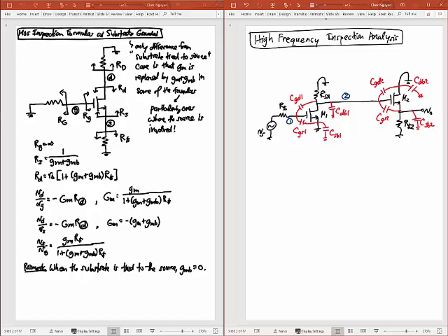And so I want to do this using the Miller transform. So I'm going to take any capacitor that is in a feedback position and turn it into Miller capacitors, because I don't want to memorize that driving point resistance for CGD, which is going to be the same equation as for C mu for a bipolar transistor. Okay, so all these equations, even for the time constant analysis, are the same as those for bipolar, except you let beta go to infinity.